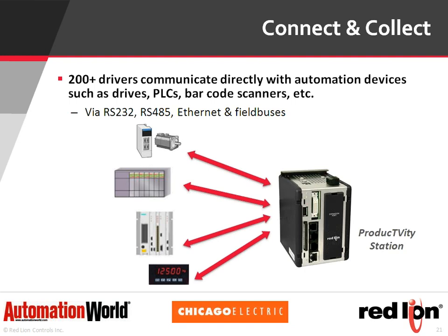Now, when looking for your own visual management solution, one of the challenges that a lot of companies face is how they get the data out of existing equipment. As I mentioned, there's software, which typically struggles at trying to get the data off the shop floor. It's good at getting the data out of the MES systems. If you decide to implement a visual management solution, you've got to consider the automation devices that you have. Do you have PLCs from a single manufacturer? Are the drives from the same manufacturer? How about the panel meters, the temperature controllers, etc.? If they're all from the same manufacturer, you might be in good shape.